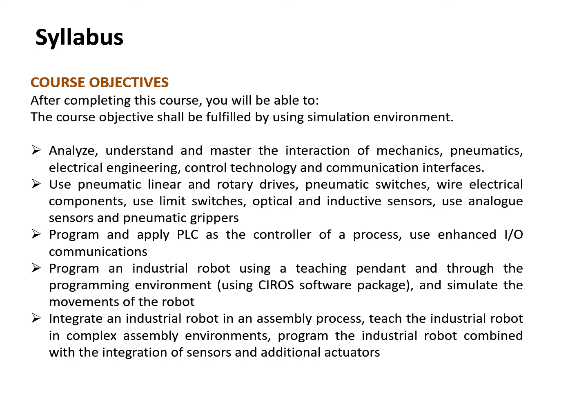Program and apply PLC as the controller of a process, use enhanced I/O communications. Program an industrial robot using a teaching pendant and through the programming environment using the Cyrus software package, and simulate the movements of the robot. Integrate an industrial robot in an assembly process. Teach the industrial robot in a complex assembly environment. Program the industrial robot combined with the integration of sensors and additional actuators.